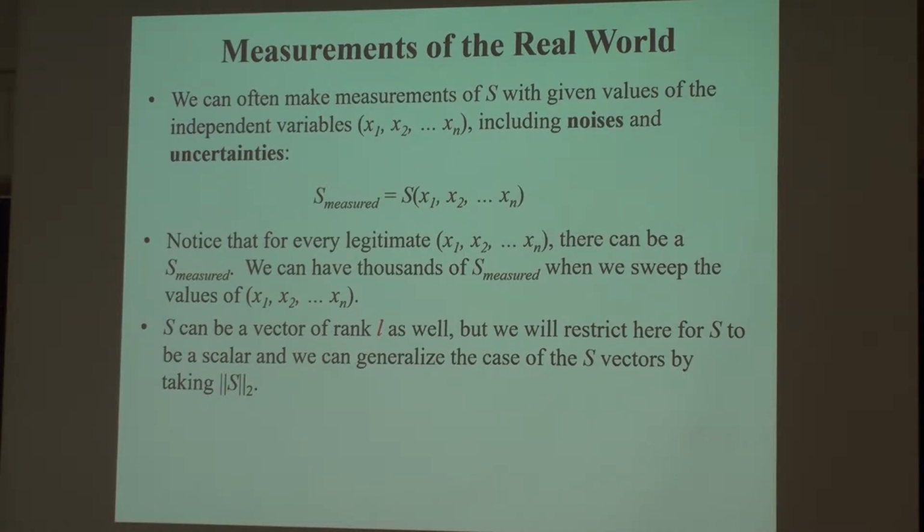So that's S, the measurement. Same thing as measuring output resistance: you set a voltage and measure the current through it. S can be your output resistance. You change all the voltages or currents, and you have a model for the output resistance containing not only the nodal voltages but also the parameters, which are those I don't know yet.